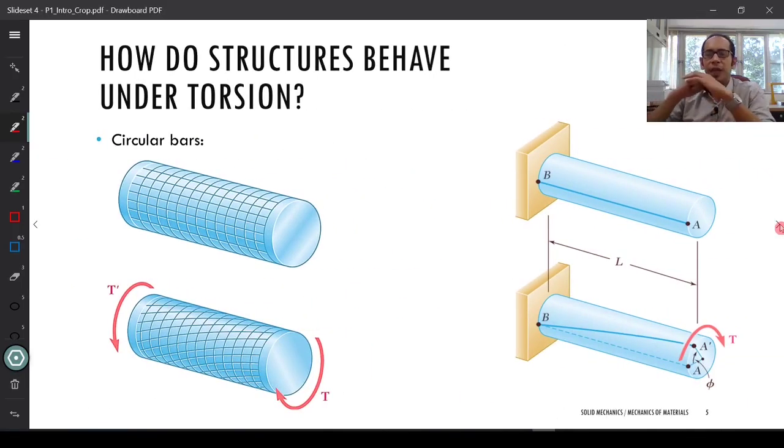So if we have to take a static snapshot of the video that we just saw, and from this figure which we just deciphered, if I have a horizontal line like this, A to B over here. After I'm applying this particular torque T, now this particular side is clamped, so if you're applying this torque T, what you will develop is an equal and opposite torque at the support as a support reaction at this particular end B over here, right?